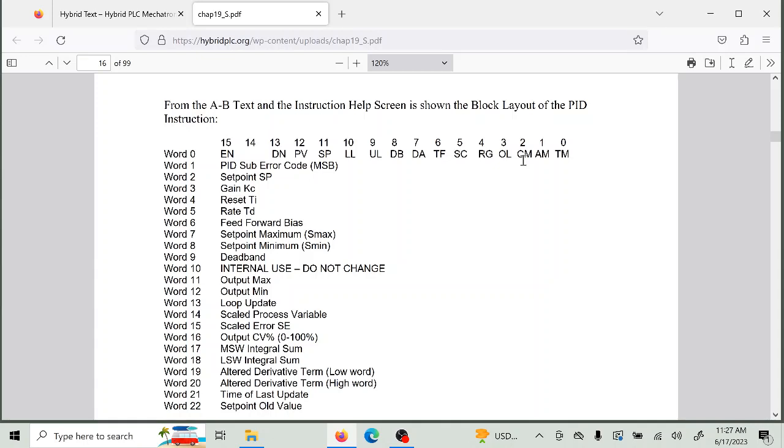So basically, this is one where you put it to a 0 and leave it as a 0, unless your output goes to 100% or 0%. In that case, put it to a 1. Flip the sign to a negative, and away you go.